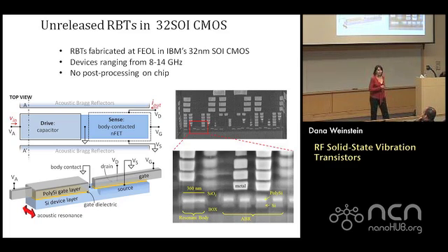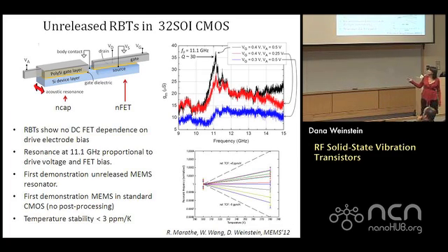But we actually got acoustic resonance, which is supposed to be defined in this direction. We got some fantastic resonances in this direction as well. As you can see here, here's the frequency response of this device. You can see the resonance designed at 11 gigahertz and some great spurious modes all around the structure. Because we were learning about the material properties of this stack, we got a quality factor of around 30 at 11 gigahertz. Now that's great for LC tanks. For acoustic resonators, you could do at least a couple orders of magnitude better.